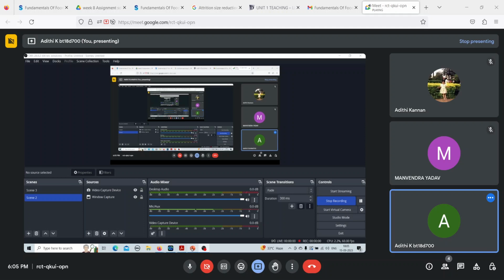Now for the second case scenario, XF remains the same, but the XP is 0.2 millimeter. For this scenario, we need to calculate the energy, and we already know that we have to use Kick's law. So if I am substituting the value in that particular equation where dE by dx is equal to minus C x power minus m, in Kick's law you substitute m is equal to 1.